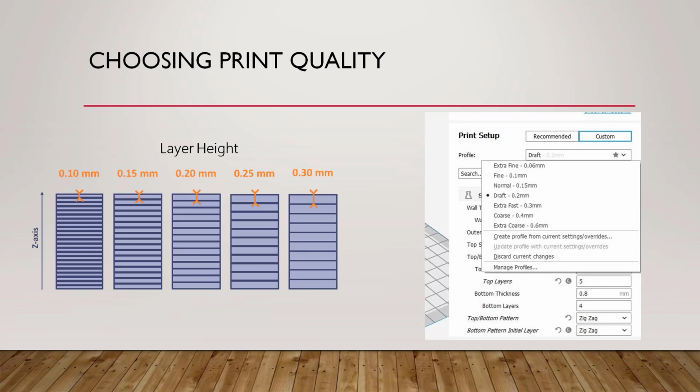So you must be choosy while selecting a layer height. If you need just a prototype and finishing is not a requirement, you can select higher layer heights, so your print will be made in much less time. If the layer height is low, then your print will consume lots of time.